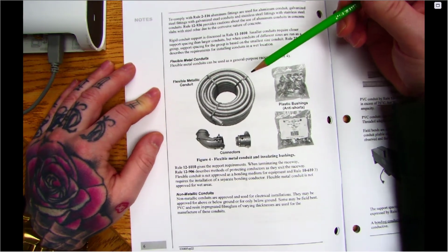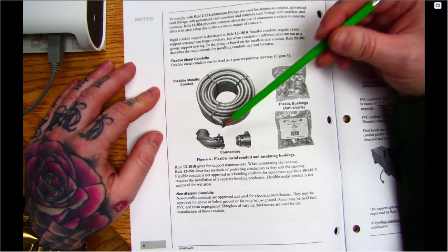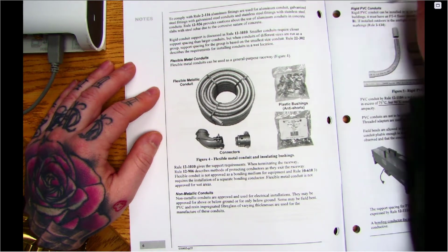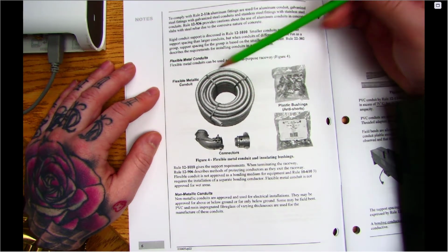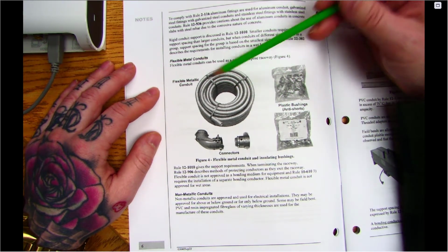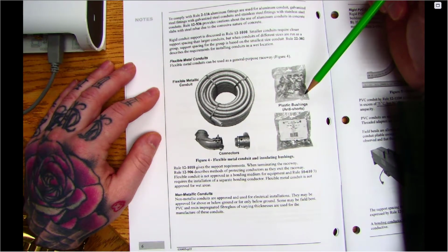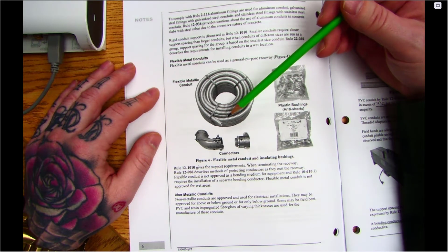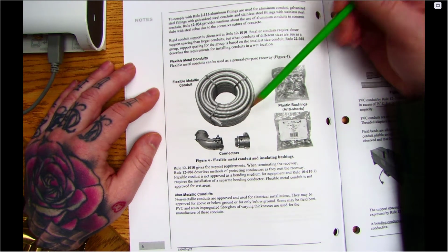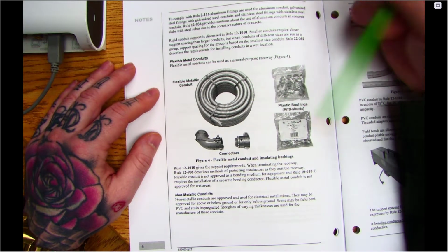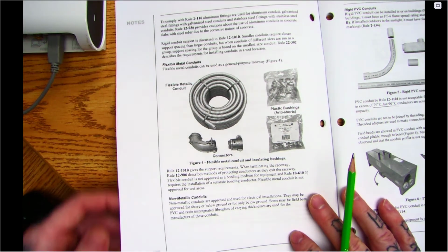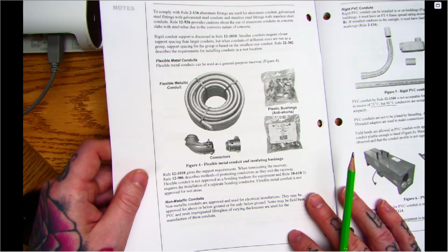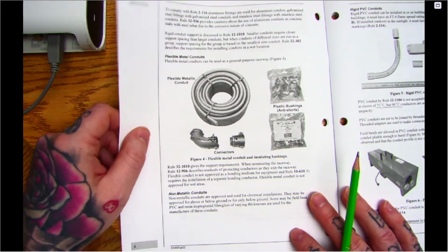So this is what we would call flex. We got our flex connectors. These are dry connectors. Okay, so there is liquid tight flex. This is not liquid tight. Liquid tight has the PVC jacket over it. Okay, but still, if it was indoors and we didn't have to worry about the weather, we could use this to go from a junction to a motor or another piece of equipment. It's handy. There are limitations to what we can use and the strapping and all that,